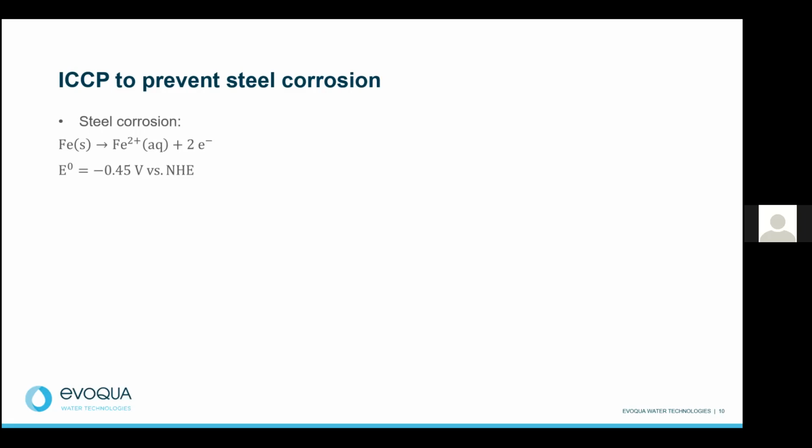And as we know, steel is easily corroded because iron is not quite the most noble of metals, as you can see in this equation. The thermodynamic driving force for steel corrosion is from the reaction with atmospheric oxygen, which likes to be reduced to water. And with no precautions, that means if you look at the reaction potentials, equilibrium potentials, any steel structure that comes in contact with air will spontaneously corrode, and it will slowly lose its integrity because of iron dissolution and rusting.